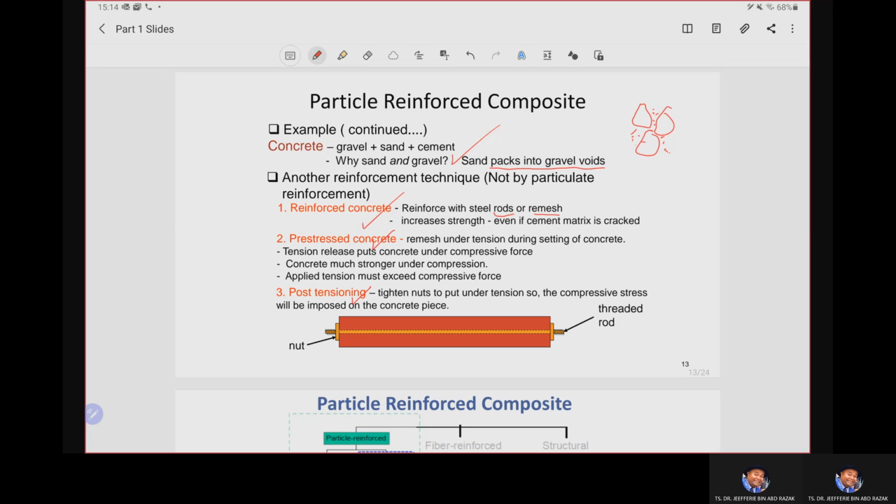How does the reinforcement increase the strength? It renders the hardened structure capable of supporting greater tensile, compression, and shear stresses. So when the concrete experiences a crack, the reinforcement available inside the concrete can still sustain the load. Another reinforcement technique for strengthening the concrete involves the introduction of residual compressive stress. So we can discuss based on pre-stress and post-tensioning.